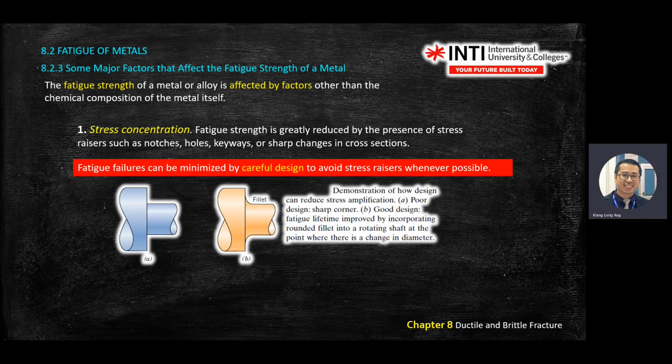One is it looks better. Another one, on mechanical properties, we know that when we remove those sharp corners, we actually improve the material properties, especially when it comes to fatigue scenario, right? Like those engine parts. Engine parts, we would like to have them in smooth corners because they keep moving in lots of cycles in the operation.